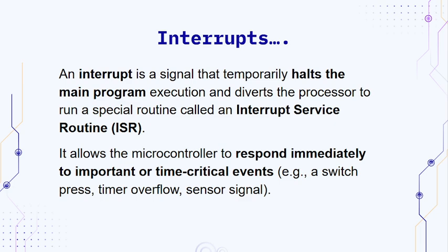So a common feature which a microcontroller has is called an interrupt. Interrupt, as the name suggests, is something which halts the main program execution and diverts the processor to run a special routine called ISR, which is the interrupt service routine.